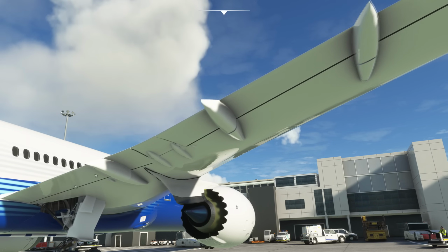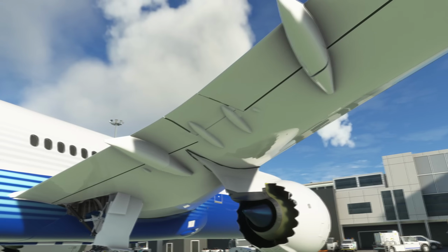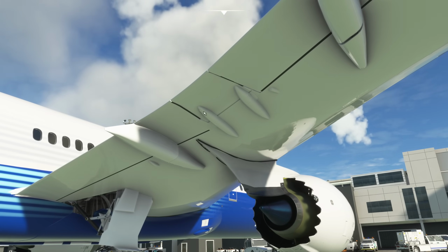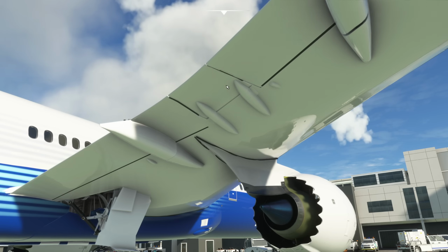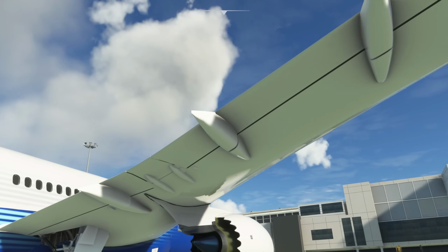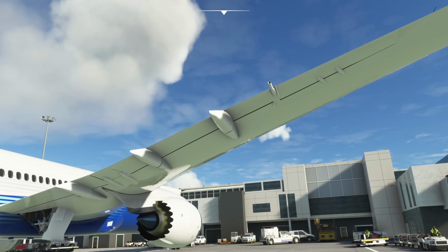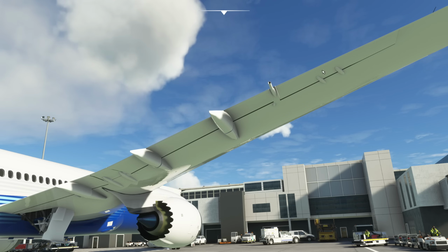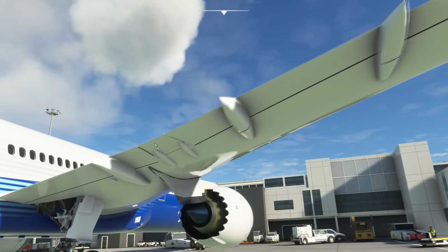Unlike the 777, where the inboard part is more complex, they've kept them quite small. They are, again, designed to be light. Here we have the inboard aileron. So this is used a lot during the cruise once you get to higher speed. The reason is you don't want to be using this outboard aileron at high speed because all you're going to do is just bend the wing around. The 787 has very bendy wings, again, composite wings, and it's great for turbulence, great for efficiency, but they do bend up a lot in flight. And if you were using this outboard aileron, it would just have a negative effect of twisting the wing around. So at high speed, this inboard one is used mainly.